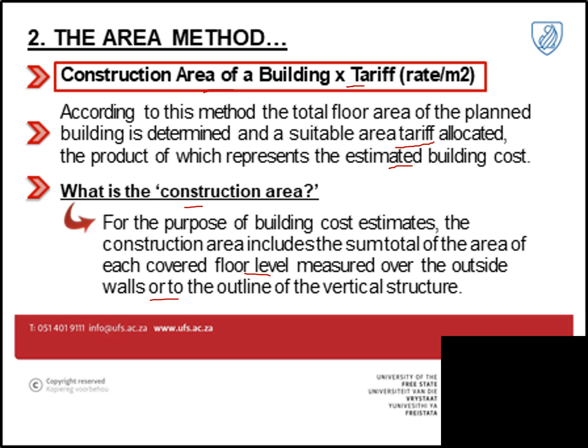Obviously, if you've got time and you want to improve your estimate, always measure to the outside of the building, because people will compare that rate per square meter to what they've heard in the industry or seen on the internet, and those estimates are usually based on the building area to the outside of the perimeter or the wall area on plan.